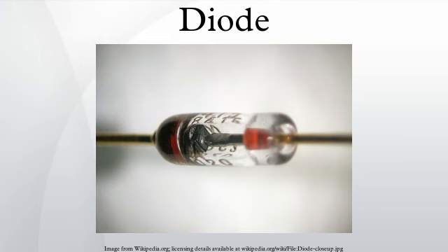Semiconductor diodes' current-to-voltage characteristic can be tailored by varying the semiconductor materials and doping, introducing impurities into the materials. These are exploited in special-purpose diodes that perform many different functions. For example, diodes are used to regulate voltage, to protect circuits from high-voltage surges, to electronically tune radio and TV receivers, to generate radio frequency oscillations, and to produce light. Tunnel diodes exhibit negative resistance, which makes them useful in some types of circuits.